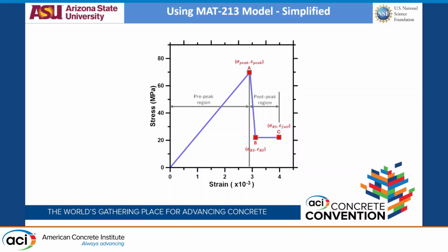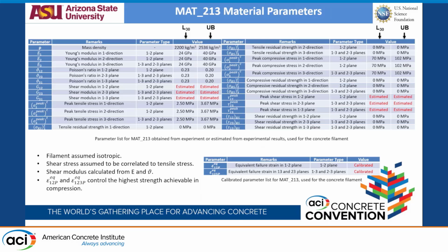But you could choose different directional parameters for the material card. Let's say this one is about 70, then I can go to another direction at 50. Again, that will be a user-specific scenario, but for our case, at least initially, we are using the same parameters for the D1, D2, D3 directions. You see there's a vast number of parameters in 213 that you have to input, which is simplified by the isotropic assumption, because the 3 directions have the same E parameters, the same Poisson's ratio, the same sigma 2, all of these. Because we have assumed isotropic, it cuts everything down by 3.